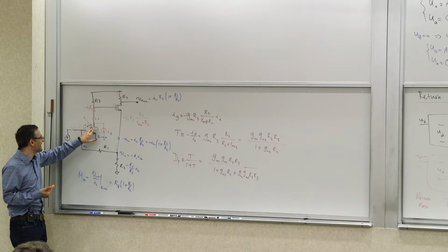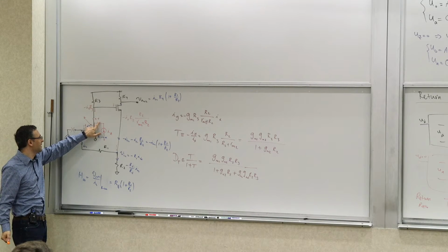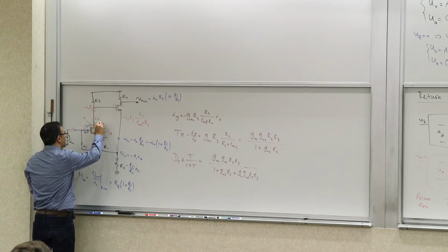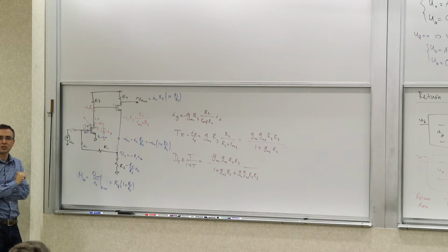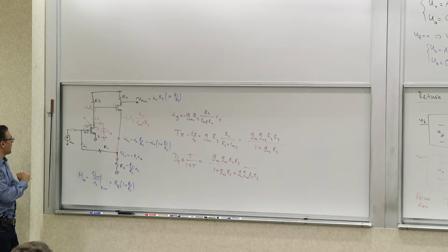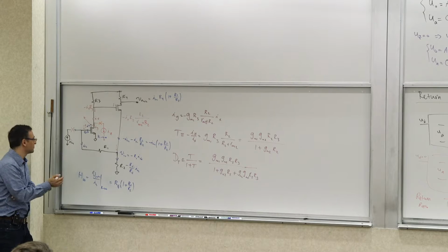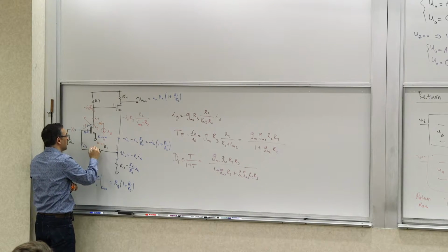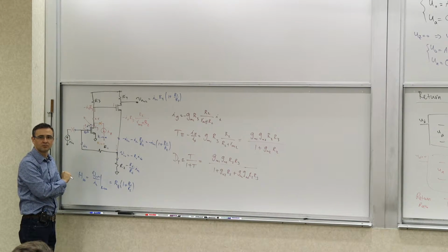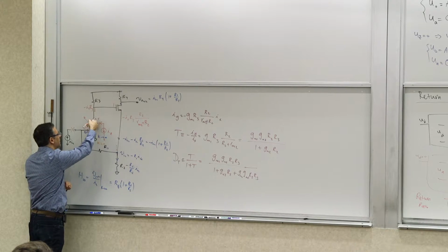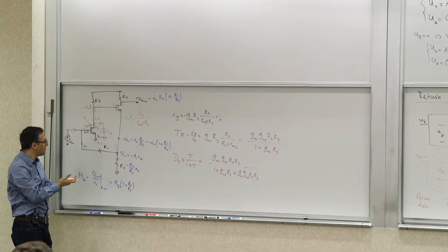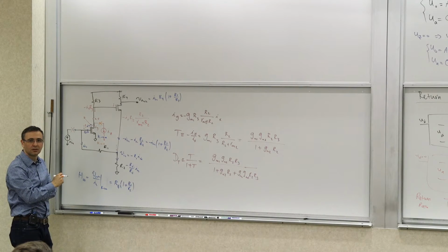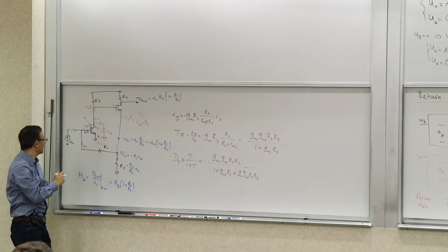For H0, we just basically kill this dependent source. So this independent source is gone for other calculations. So this is not there. There's a dependent source in here, that's the dependent source of the hybrid pi model, right? So when k equals 0, that source is gone. So there's no signal generated here. There's nothing going here, right? So would there be any signal at the output? Is there another path for an input signal?